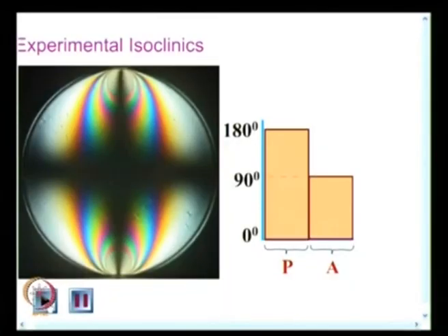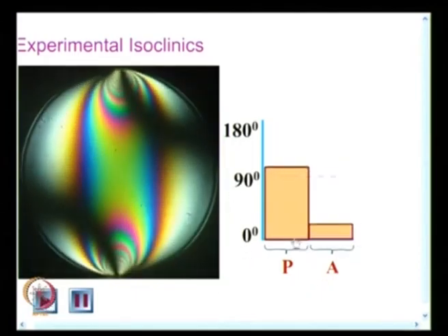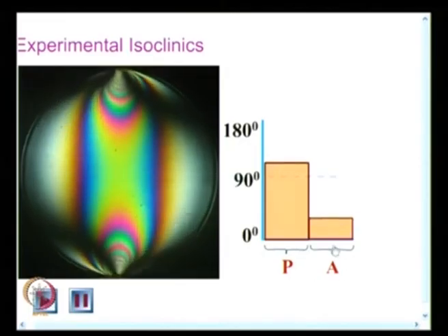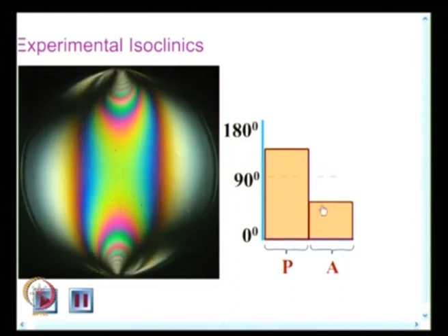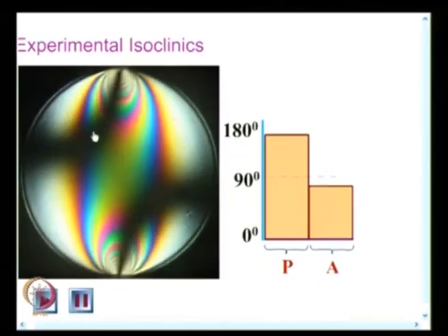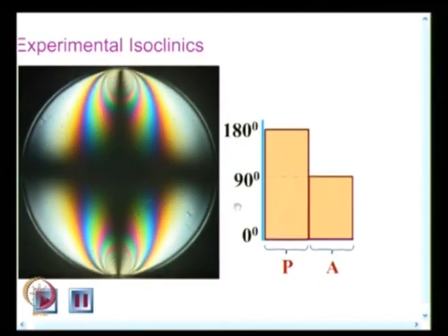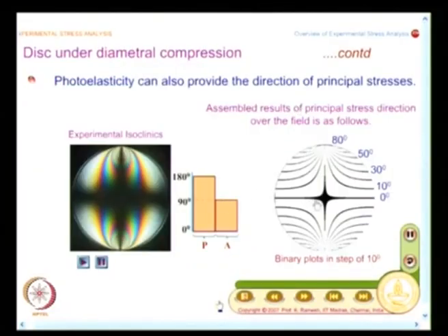And in this example, I have one set of contours that move, and this you may not be able to understand at this stage. What it indicates is the direction of the polarizer and analyzer. These are two optical elements, kept at mutually perpendicular orientations. For these angles, these contours move. So, from a data collection point of view, I have to set them at fixed angles and try to make a reasonable sketch of what these contours are, and that is what is shown here.